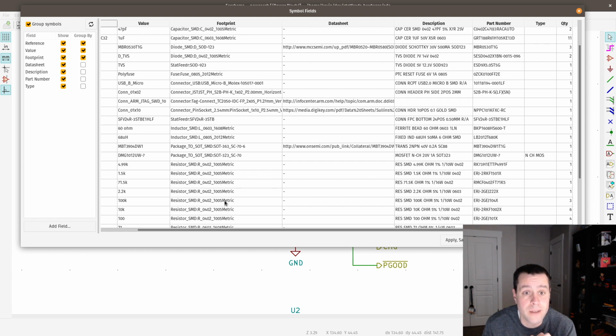That's something that I figured out the first round through, that it gets hard to manage these bills of material when you've got all these different resistor values. And I did a video a while back where resistors and capacitors come in and out of stock, capacitors especially. The global supply of those is very short, and so you have to change those part numbers every run that you do. And so the fewer parts that you have to do that for, the better and the faster you get.